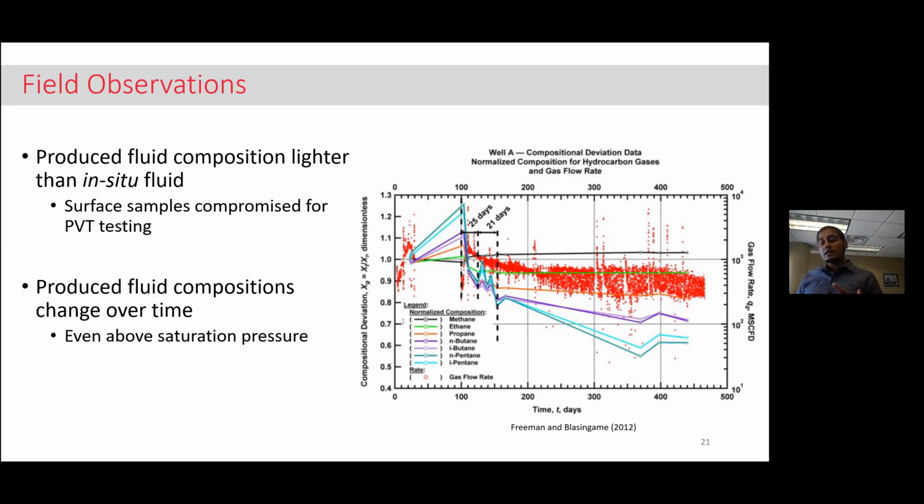Turns out that with the shales, we actually do observe that the compositions are changing, even if our producing bottom hole flowing pressures are above the saturation pressure. And that's extremely strange because that flies in the face of everything that we've learned about fluid flow and maintaining things.